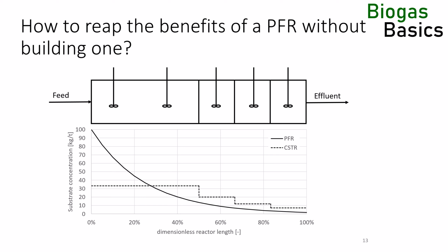I made the first compartment larger than the others. This has 2 reasons. Reason number 1 is to lower the average substrate concentration in the system. While the CSTR-cascade does not show the substrate conversion performance of an ideal plug flow reactor, it also does not show the high substrate concentrations at the beginning of the plug flow reactor. In a theoretical first-order reaction approach, the high substrate concentration would generate a high reaction rate, but in the reality of a biogas reactor, the high substrate concentration would lead to acidification. Also, high substrate concentration would mean high viscosities and high concentration of undigested dry matter. So lower substrate concentration can be beneficial to the overall process.